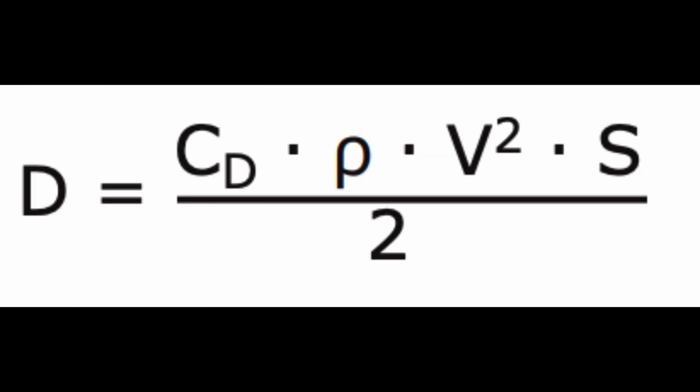The L/D ratio is determined by dividing the CL by the CD, which is the same as dividing the lift equation by the drag equation, as all of the variables, aside from the coefficients, cancel out. The lift and drag equations are as follows. L equals lift in pounds, D equals drag, CL equals coefficient of lift, rho equals density, expressed in slugs per cubic feet, V equals velocity, in feet per second, Q equals dynamic pressure per square foot, Q equals 1/2 rho V squared, S equals the area of the lifting body, in square feet, and CD equals ratio of drag pressure to dynamic pressure.